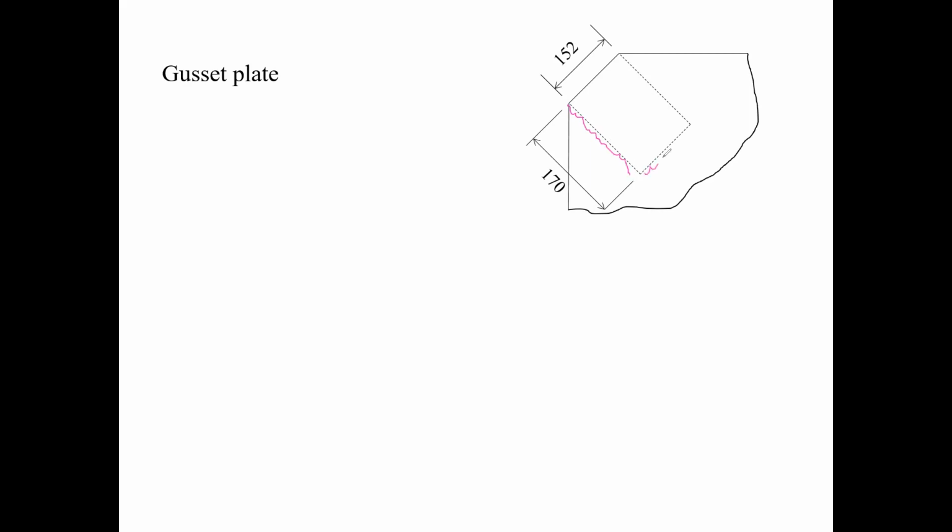You're welding along here, and you're welding along here. And therefore, if you're going to have a block shear, most likely this is the piece of metal that's going to shear out of your connection, and that's what you don't want to have. And you've seen that in the photo series last week. You can have block shear occurring, okay?